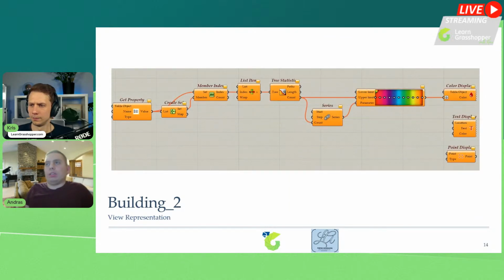If you want to display something in a different color in Tekla, we need to create a custom view representation. For this, various settings must be manually generated in Tekla, such as the view filter. With Grasshopper, this process can be done more easily, even by using this code as shown in the image.